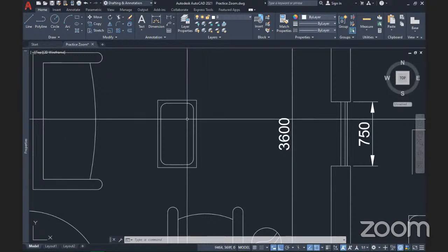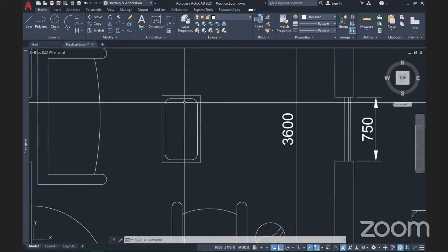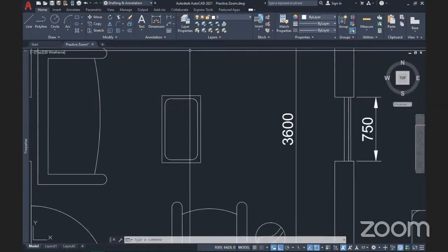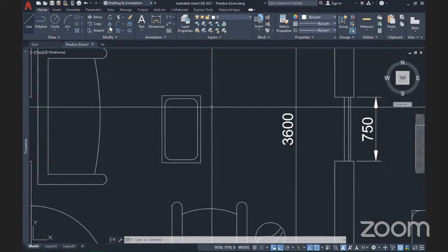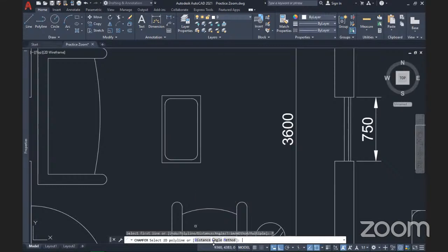So that is it for the chamfer and fillet. Let me apply a chamfer to this table inside of the house so it will look like an investor's table. Come here, select chamfer. And of course, I'll make it a polyline, so it chamfers all the edges at once.